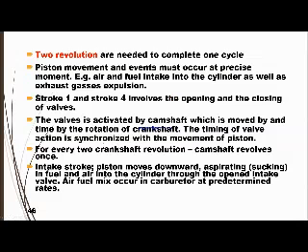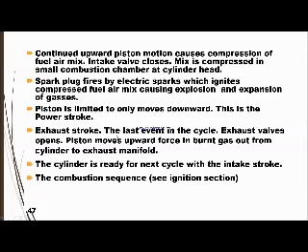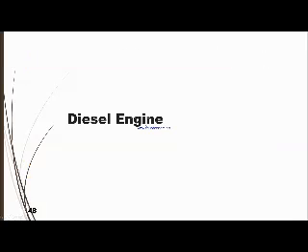All right, so for the main components of combustion in a gasoline engine, two revolutions are needed in order to complete one cycle, or one unit of power production. Other than that, you need to know when the valve is open and when the valve is closed, and by how many degrees of rotation. That's the main parameter that you need to understand. Others are pretty much the same as mechanical operation. So I'm not going to cover this.